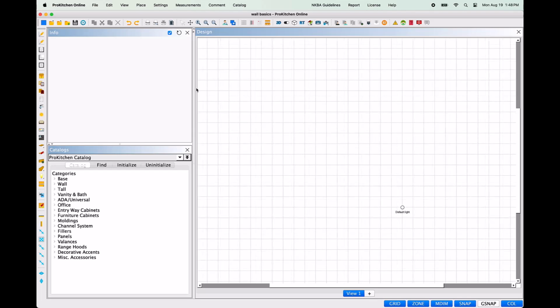To draw walls manually, navigate the mouse to the Sketch icon at the top of the left toolbar and left-click to select. Then bring your mouse into the plan view. The cursor has now become a crosshair, which indicates the mouse is in edit mode and ready to complete an action.